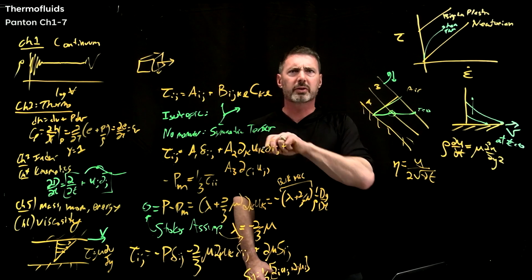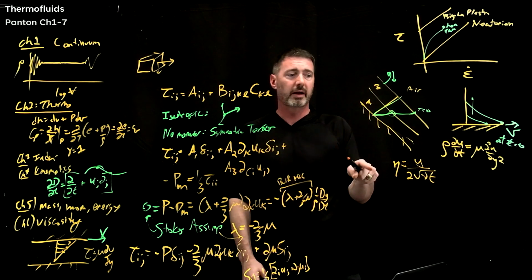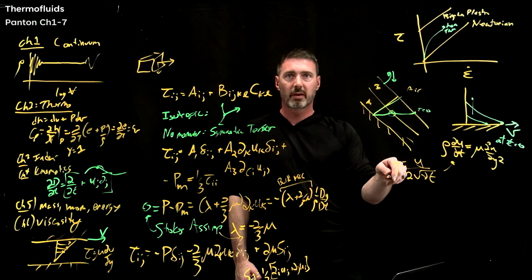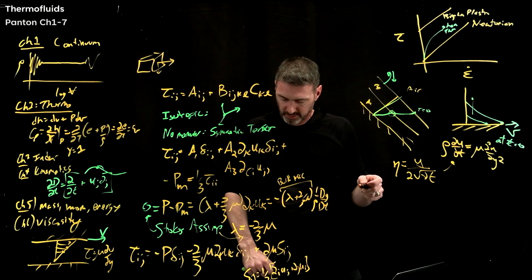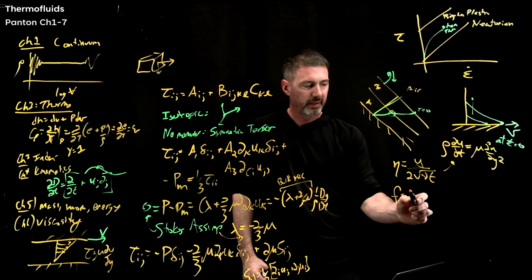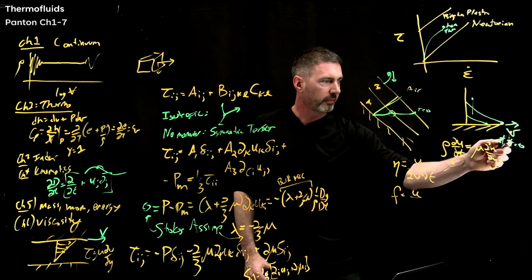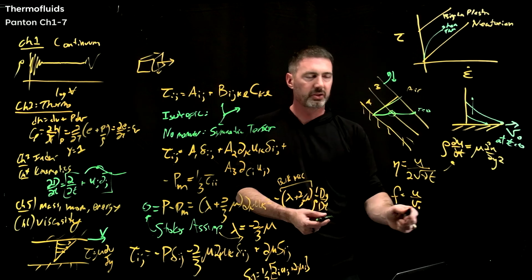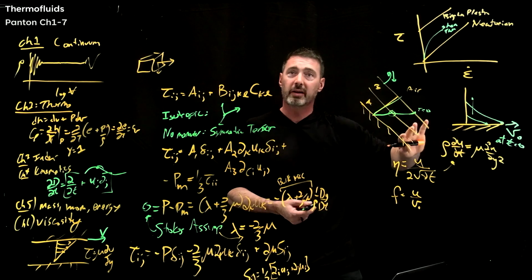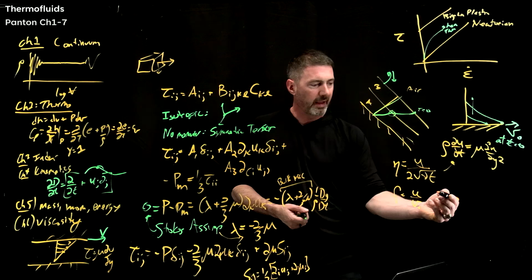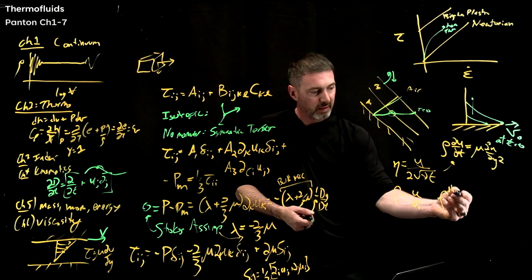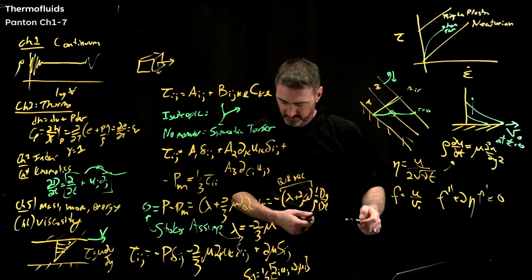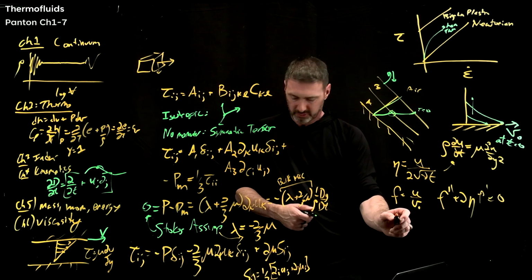So I think it was maybe last lecture, the one before, we talked about the Blasius boundary layer, where you had, again, this variable eta. And so the work is you transform this equation using eta, and then you define f to be the velocity over, let's call that v naught, that initial tug. And it's a constant tug. As soon as you start tugging, you keep tugging. That's f. You'll then end up with a differential equation that is f double prime plus 2 eta f prime equals 0, which has a very easy solution.